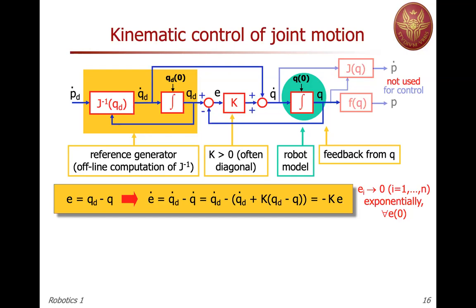So you assume that the low-level controller is ideal. In fact, it is not. This is why I introduced these examples in the beginning, to understand why we cannot increase K arbitrarily. But indeed, the best choice would be the largest K possible, until we see that the behavior is not what we expect. We are getting into the bandwidth limit of our low-level control loop.